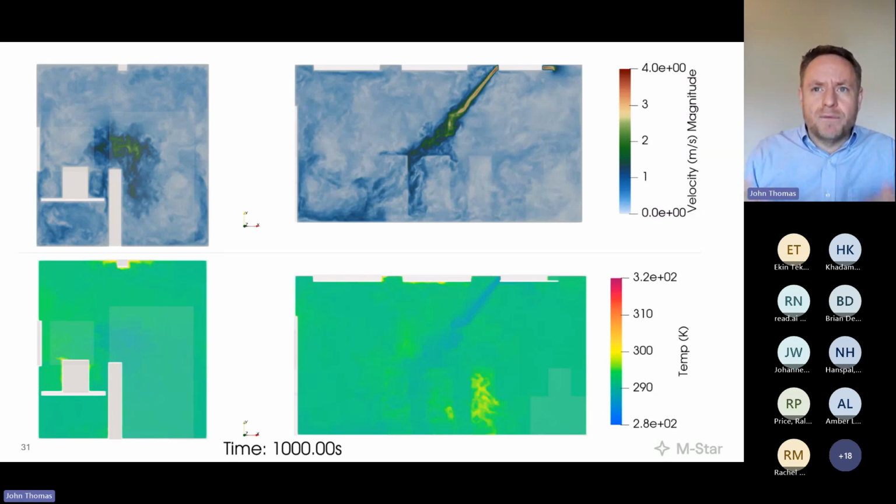It can comfortably handle the 10 million time steps required to simulate an hour of process. It can comfortably handle the 100 million lattice points required to achieve the resolution necessary to see the computer keyboard on the table in the room that's 20 meters long. That's where these types of GPU approaches shine, because in doing so, you don't have to simplify your model and say, well, here's a mean flow field. We'll slap some particle tracers on there and see how it goes.